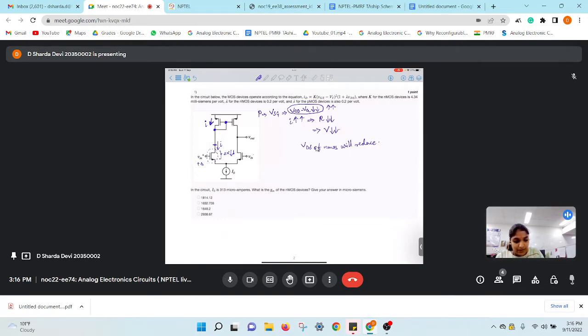The same gate voltage is applied across the other PMOS, so there will be i amount of current flowing through it too. We can call this the current mirror effect, the similar action of how a current mirror circuit works, just in PMOS configuration.